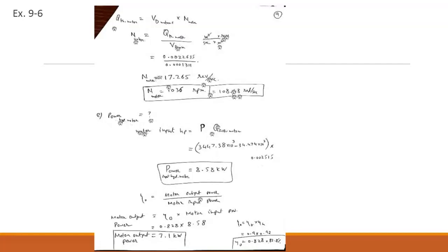We have now PQ, the hydraulic power that is produced. P is the pressure, and Q is the volume flow rate. Here, please pay attention, guys. Here you see the discharge pressure is subtracted. Why? This is the total pressure entering the hydraulic motor, and this is the pressure which is still there, which is not utilized by the hydraulic motor. So this is the discharge pressure, and this is the inlet pressure.